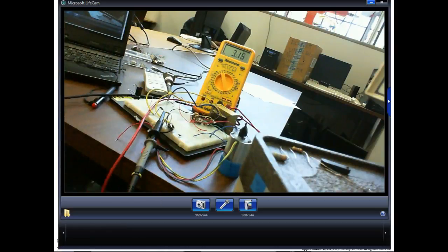So that gives people problems too. What it does is, even though it's DC, it's taking the RMS value of that DC, right? You understand? So make sure your meter is on the range that you're checking. AC is pretty easy, because if you put your DC meter in an AC circuit, it's going to measure 0. But if you put your AC meter in a DC circuit, it's going to measure something. But it's going to be what? It's going to be wrong.